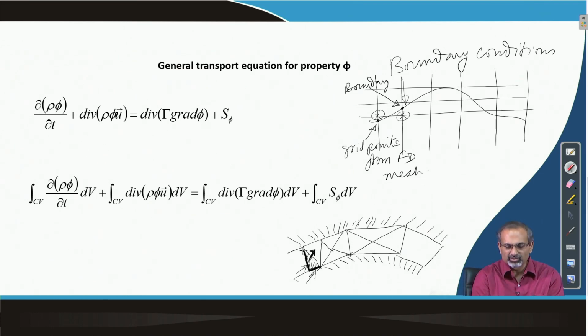And then when it goes out to the neighboring cell here through one face only, and then the neighboring cell exactly transfers the same mass into this cell. Once it gets into this cell, it has freedom in transferring mass through two faces to neighboring cells and so on. So, mass will never get lost anywhere, conservation is guaranteed.